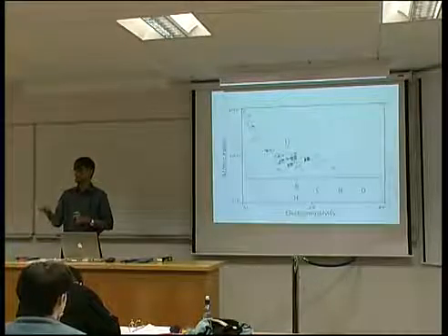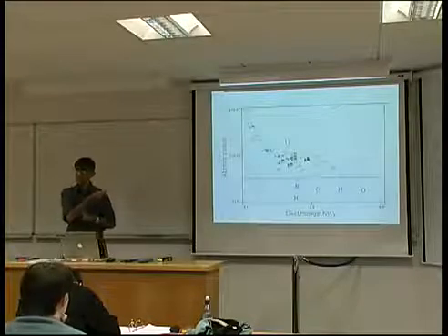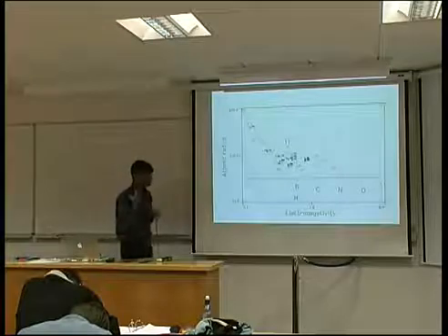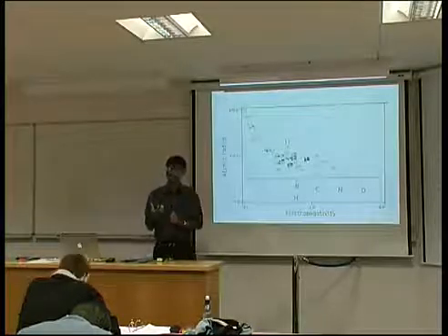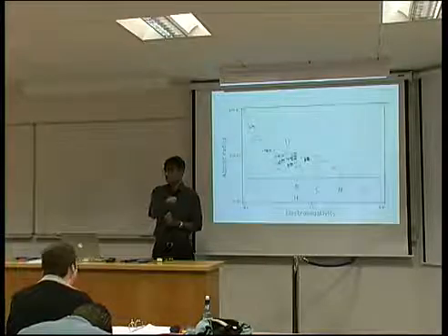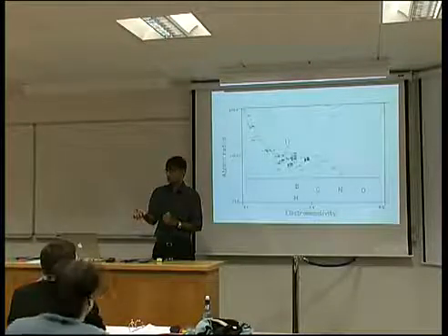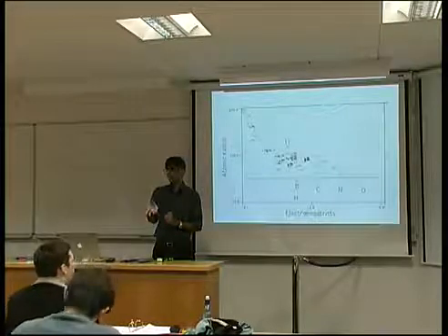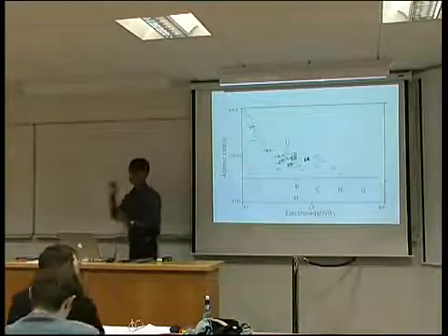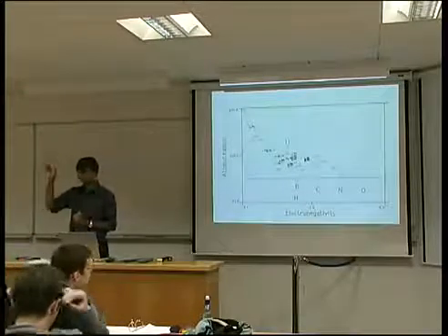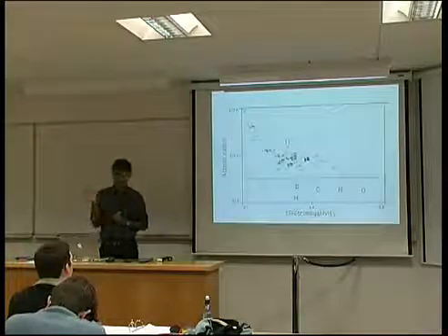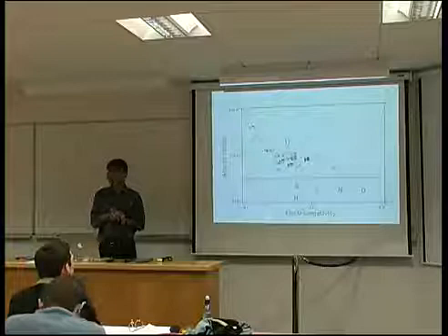There's no need for you to remember which elements. I'm just giving you an indication of, if you want substantial solubility, then you will get interstitial solution when the atoms are less than 0.6 of the host atom, and substitutional solution when it's between 0.85 and 1.15 of the radius of titanium. And beyond that, there's very limited solubility. This applies to any alloy system, not just to titanium.